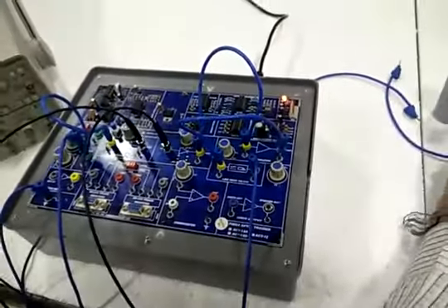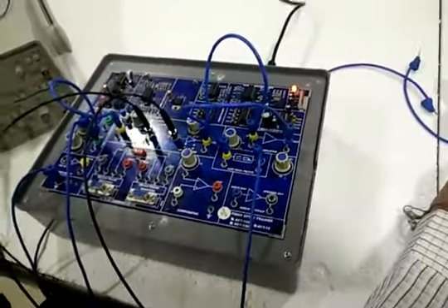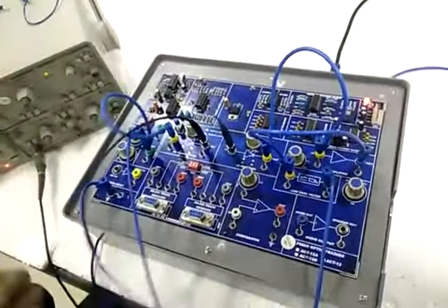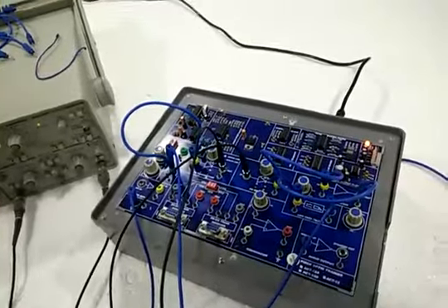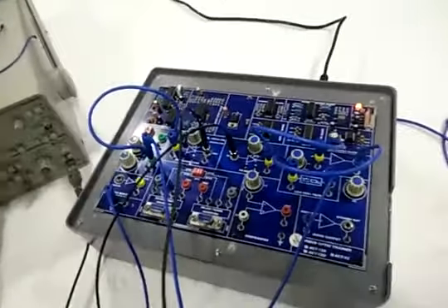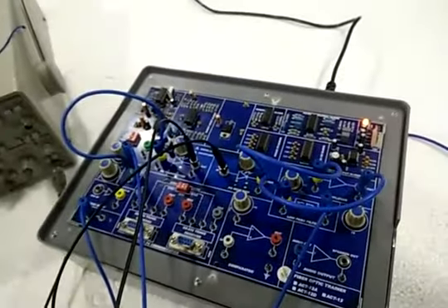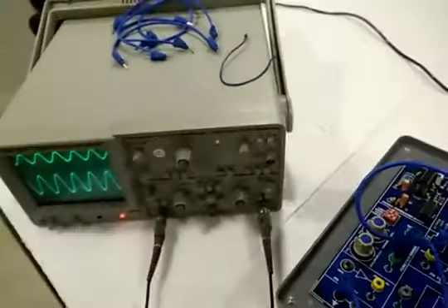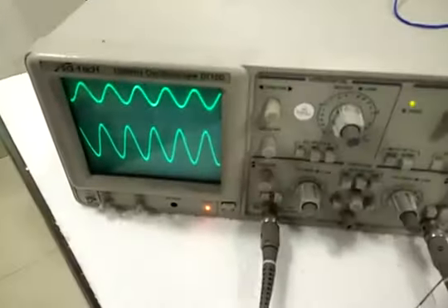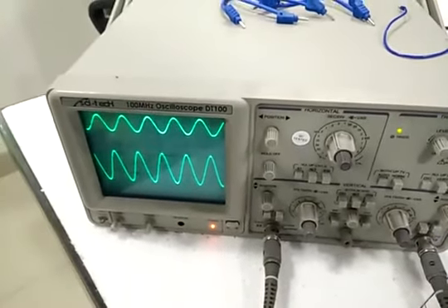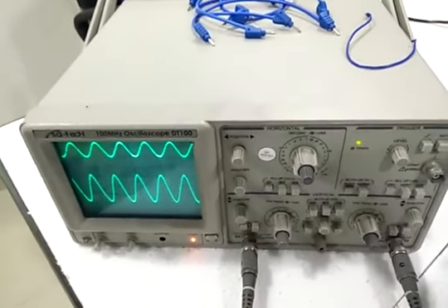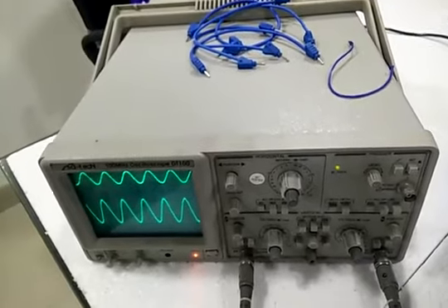Now we will see other experiments related to analog link. Study of bending loss. For this experiment, keep the setup as it was for analog link and measure the output voltage. This is the output voltage without any bend in the fiber optic cable.